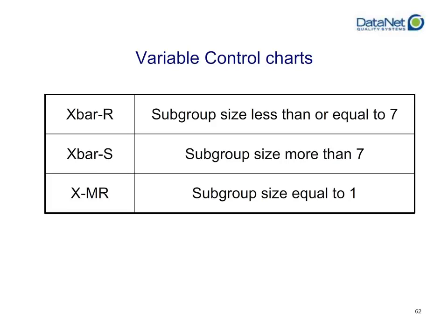However, your mileage may vary based on what you're trying to do with your process. You plot your X-bar, that's the average of your subgroup, and the R, which is your range, your largest minus your smallest value within your subgroup. You plot it on a combo chart, a top chart and a bottom chart.